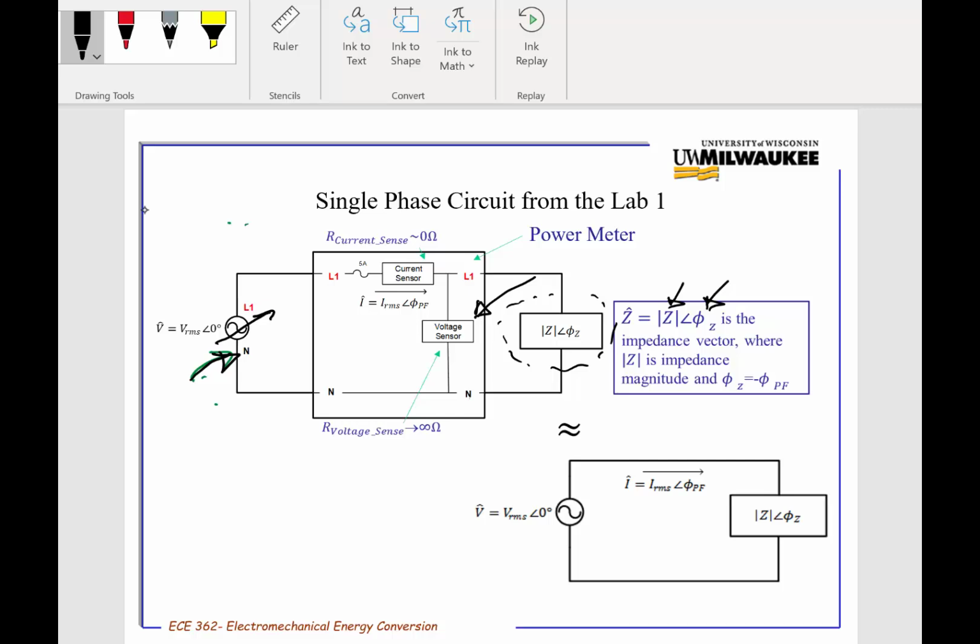It also has to sense the zero crossings of the voltage and compare them to a signal measured through a current sensor with a nearly 0 ohm impedance. Then it calculates the power factor angular difference between the voltage and the current, and the RMS current. So you're really going to see in your meter's readings voltage, current, and power factor angle.